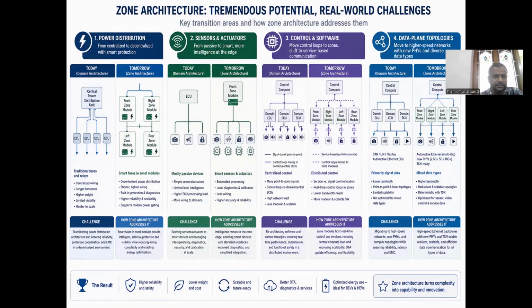You can scale it when you would like to. And there is something called module power gating. What is module power gating? They use something called a sleep switch in these zone controllers. They shut off the power when a particular sensor or actuator is not used. When it is used, the power is supplied.